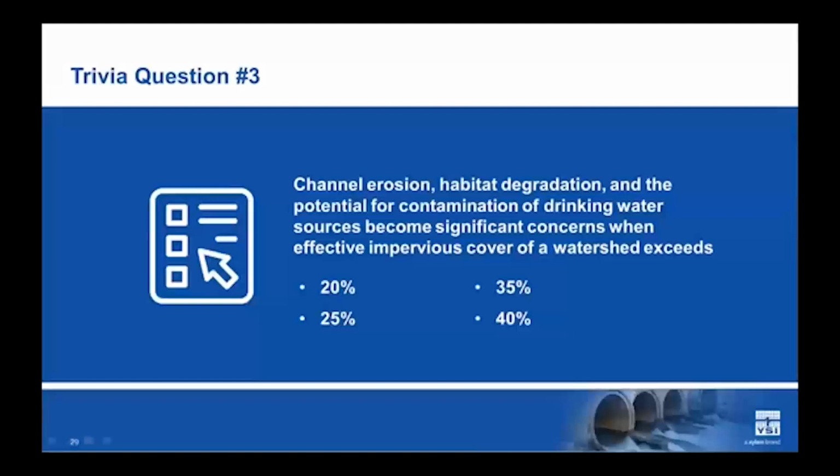With a radar and ultrasonic, if that creek bed goes dry, a lot of times you get these weird transmissions back to the sensor because all of a sudden you're exposing rocks and that surface can change. You don't have any of that to worry about with a bubbler. So I love bubblers for stormwater monitoring. I think they're a great solution when you're in those sites that are tributaries that are not always filled with water.